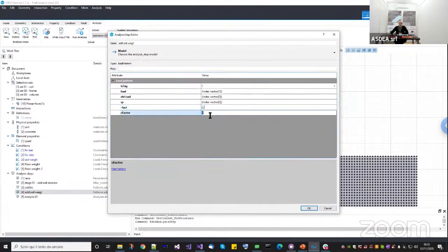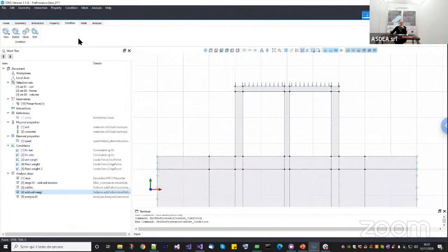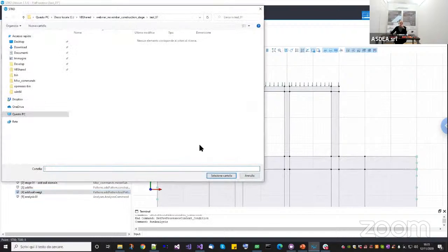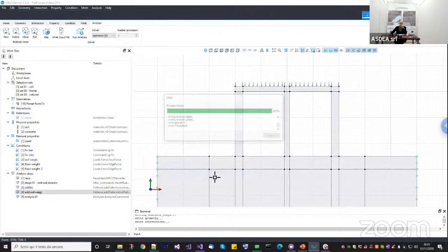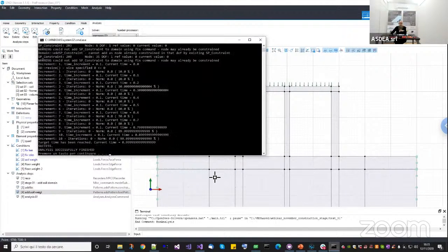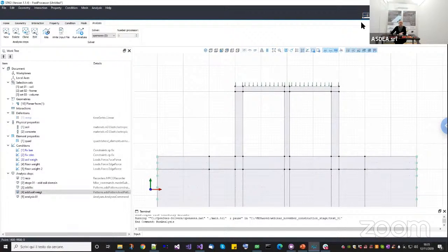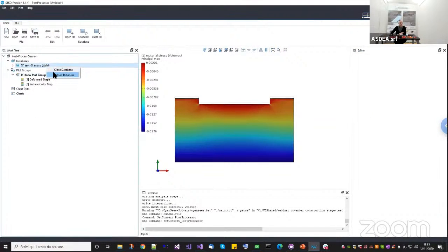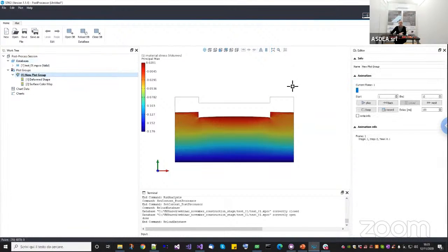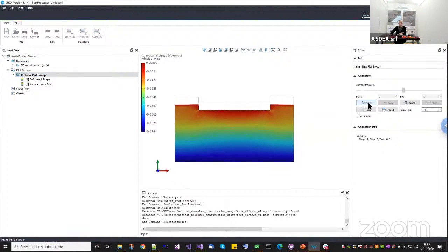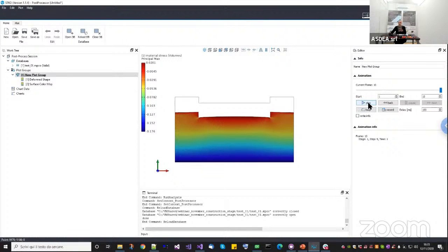In fact, you will see that in the example that you will see tomorrow on our website, the self-weight of the soil has been increased by 10 times. Not because it is a real number, just to have a proper visualization when I will put the structure on. Okay, so let me rerun it. Okay, and we reload it. Okay, so this one is the behavior that I expect in here. As you can see, the entire model is not in the domain, only the soil.